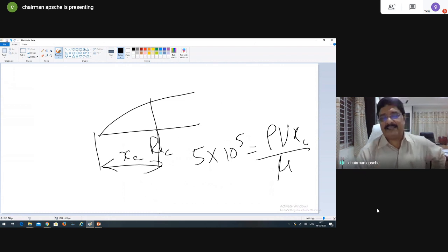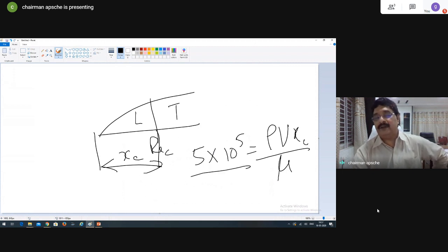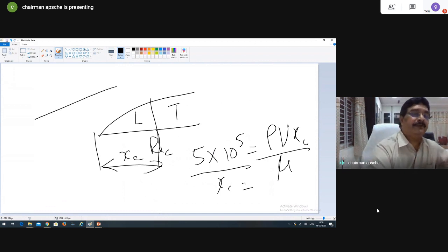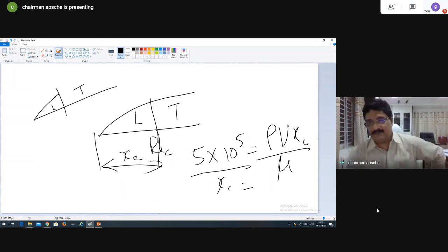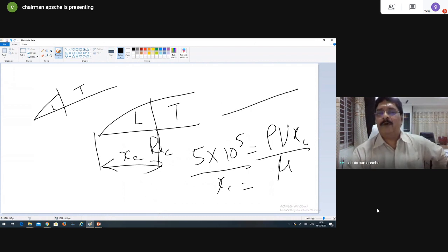And the X critical, when I say XC, it is at that point flow starts changing from laminar to turbulent. So, you know rho, V, mu and you know the standard value of critical Reynolds number, you can calculate XC. Once you calculate XC, then you will be in a position to say, okay, till that distance it is laminar, thereafter it is turbulent. And normally, in a plate of longer distance, when laminar is for a short distance, particularly with high velocities, we assume that fluid flow is turbulent right from the beginning.